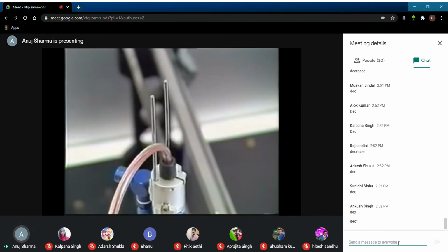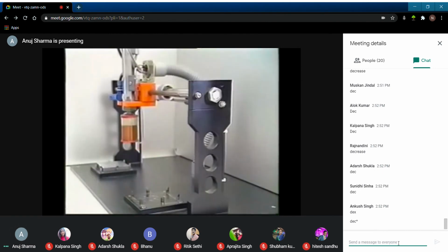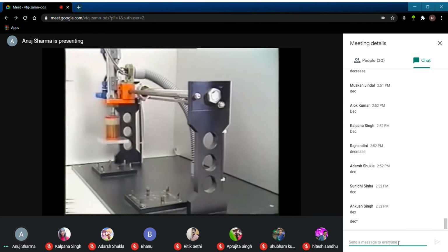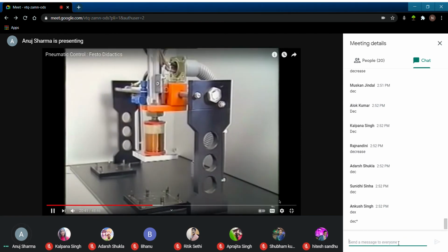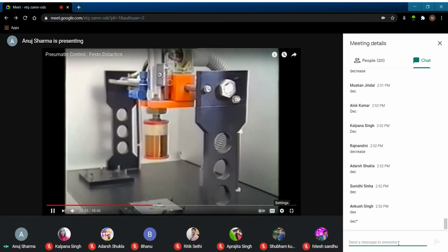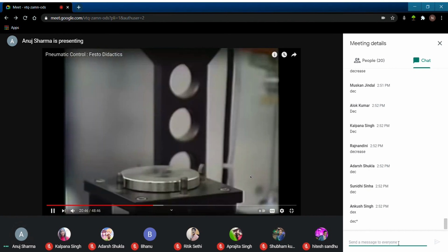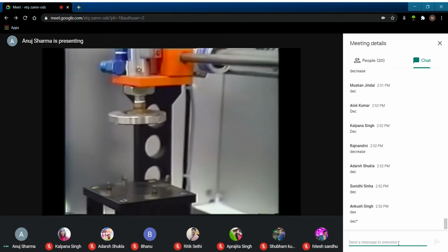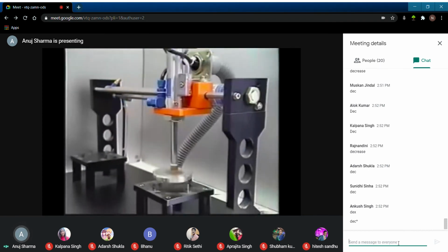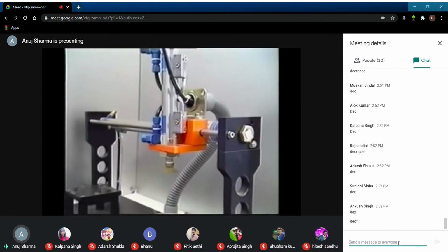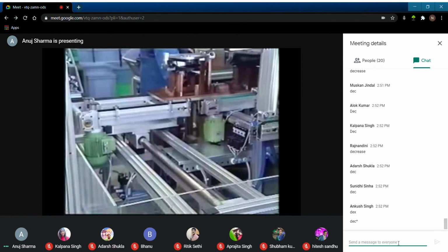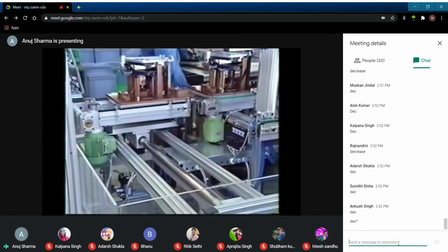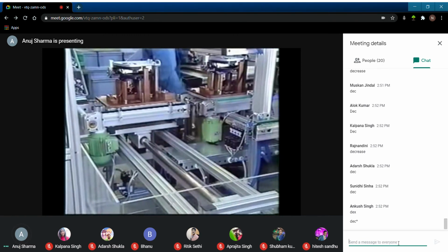Another type of cylinder design has a hollow piston rod. This can be used to hold wires connected to a device at the end of the rod, such as an electromagnet. Or it can be used as a passage to carry vacuum or liquid such as oil. These cylinders have a fitting on the end of the rod for the connection of the tubing. This cylinder has no piston rod.